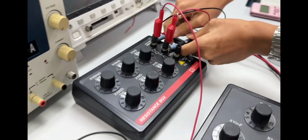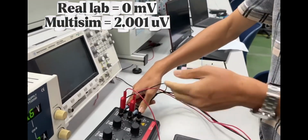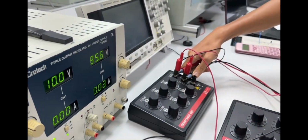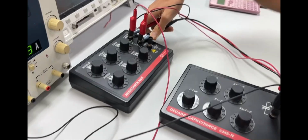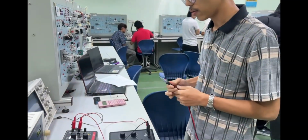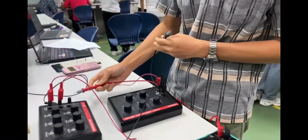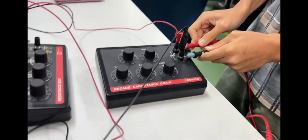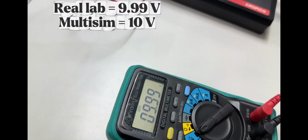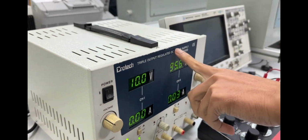As we can see, the value is 0 because the current going through from the DC supply has been charging the capacitance. That's why the current does not go into the resistance. Now I will measure the voltage for the capacitance. The voltage for the capacitance is 10 volts, the same as the voltage output from the DC supply circuit.